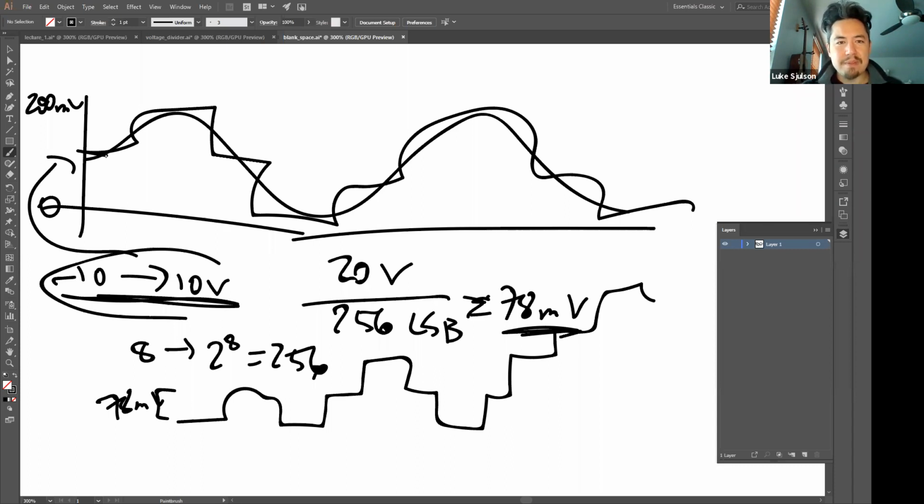So you can look at this two ways. One is that it's a crappy piece of hardware, having an 8-bit DAC. If you think about that, that's really not very good. The newer ones have 12-bit DACs, which is much better, so you can have 2 to the 12th values. Actually, let's think about that for a second: 20 divided by 2 to the 12th. So there you have a resolution of 4 millivolts. 4 millivolts would probably be enough for most things.